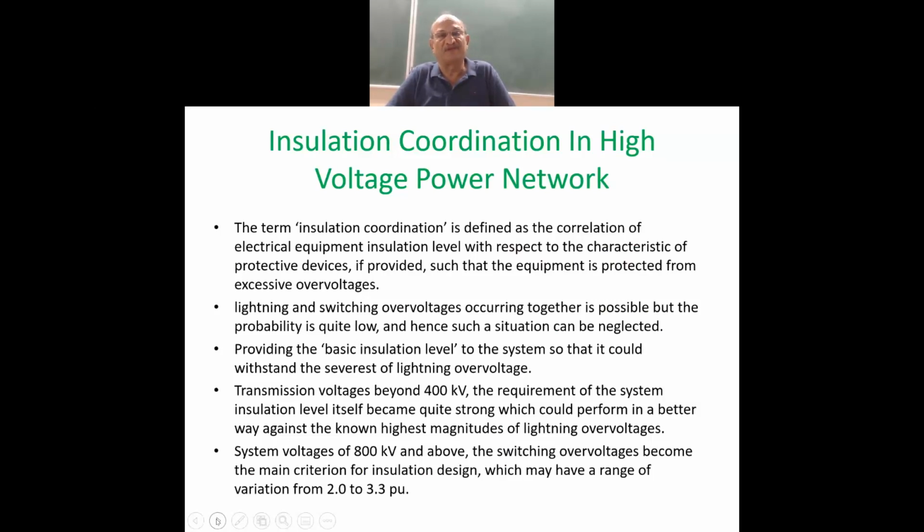The flashover voltage between any two electrodes may become different over time. So they used to malfunction, requiring a higher flashover voltage because of corrosion. When they should flash over for the overvoltage, they are not doing so. That means they are letting the higher magnitude of the overvoltage pass on to the network.